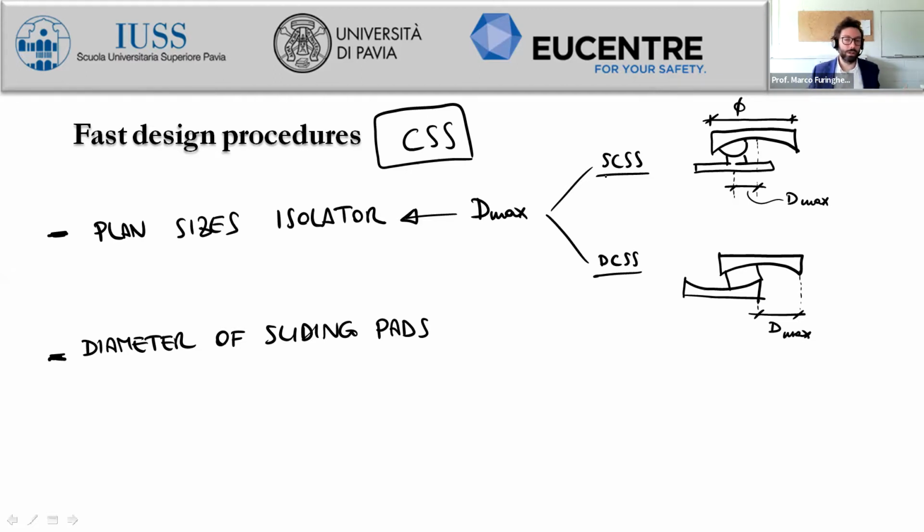You achieve the same value of peak displacement, but the device itself is smaller if you consider two sliding surfaces with respect to one. It is like this because you gain the maximum displacement in two individual surfaces, rather than in the first device, where the total amount of displacement is on the main sliding surface.